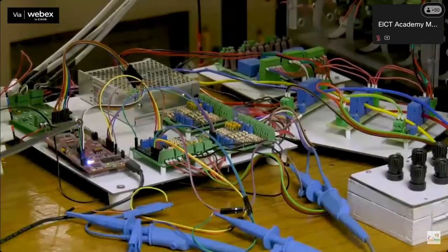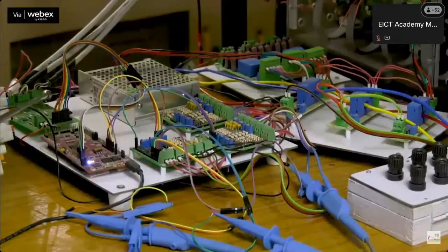Here, the DSP generates PWM pulses at a voltage range of 5 volts. The switching voltage range of the IGBT present in the Semikron stack is around 12 to 18 volts. The generated 5 volt PWM pulses alone are not sufficient to drive the IGBT switches. For efficient triggering of IGBT switches, the generated PWM pulses from the DSP are shifted to 15 volts by using a level shifter.